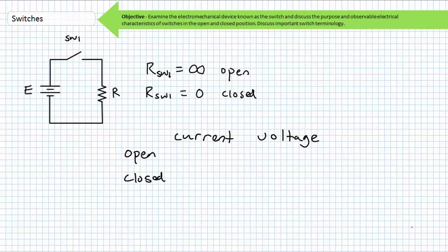These facts bear repetition since they are essential to understanding observed electrical characteristics of closed and open switches. A closed switch will allow current to flow. An ideal closed switch, being a 0 ohm resistor, will have no voltage dropped across its two terminals. Although in practice a real closed switch does present a measurably small amount of resistance and therefore might experience a tiny voltage drop. An ideal open switch, being an infinite resistance, will not allow current to flow.